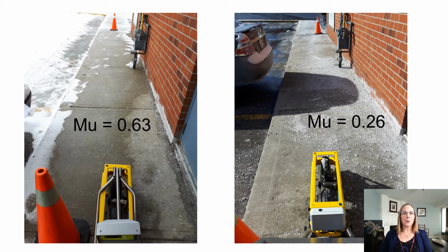These 2 photos are a great example of what it means to use salt correctly. The picture on the left shows a walkway where the salt has melted the snow and ice, and there's very little left over, and it has a relatively high mu of 0.63, so it would be considered pretty safe to walk on. This is exactly what we're talking about when we discuss the right amount of salt. It's enough to melt the snow and ice, but there's very little of it left over to dissolve and end up in our water bodies.